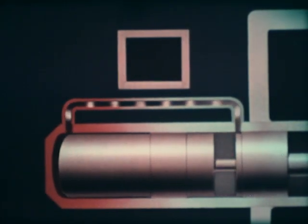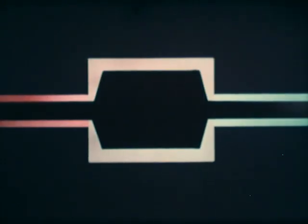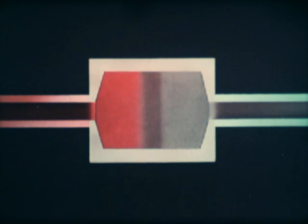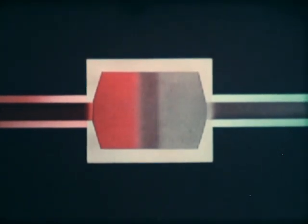This may be done with a so-called regenerator, a chamber filled with a porous metal which acts like a sponge. During one half of its cycle, the gas gives up heat to this chamber, only to take the heat back on its return. A version has now been developed which enables more than 99% of the heat to be recovered, without offering too much flow resistance.